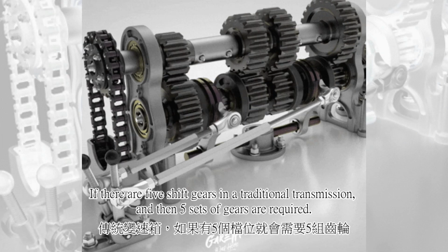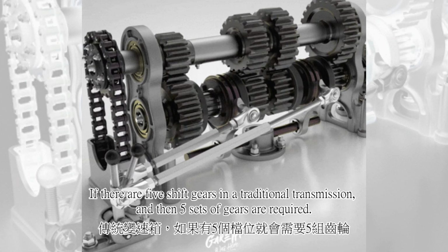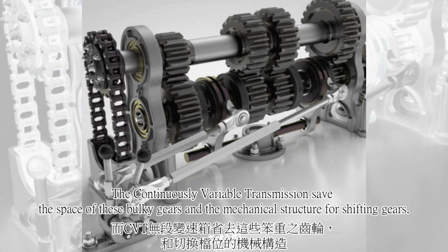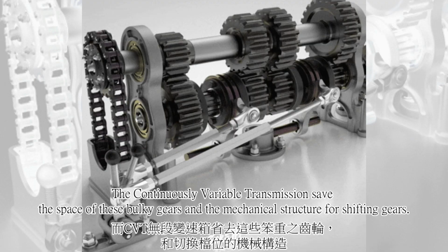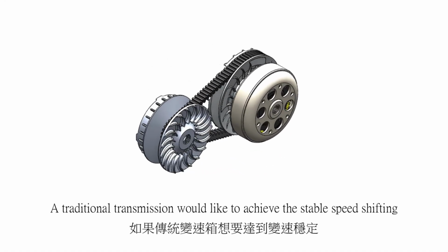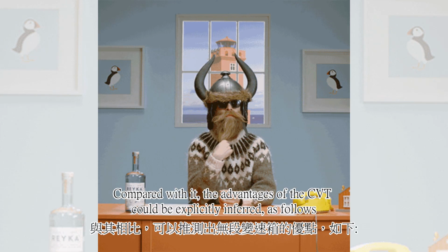If there are 5 shift gears in a traditional transmission, then 5 sets of gears are required. The continuously variable transmission saves the space of these bulky gears and the mechanical structure for shifting gears. A traditional transmission would need to use a lot of assembled gears to accomplish effects similar to the CVT. Compared with it, the advantages of the CVT could be explicitly inferred as follows.